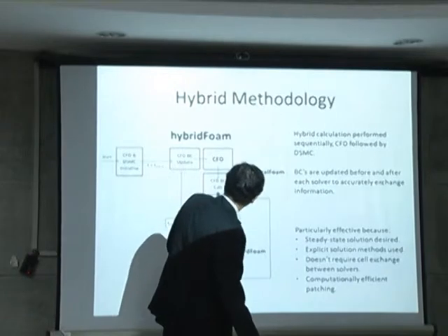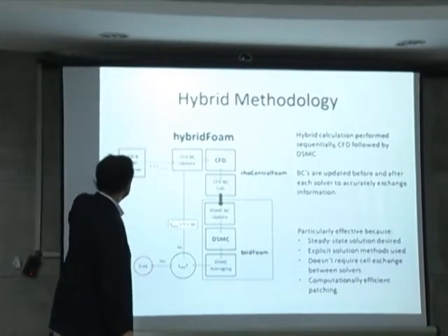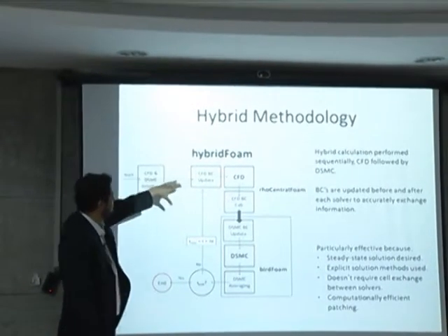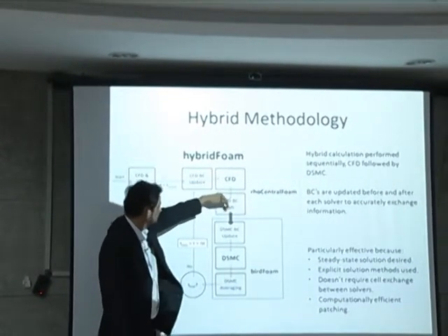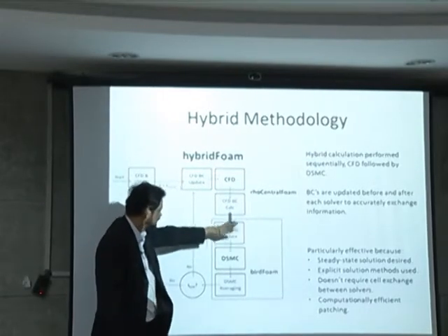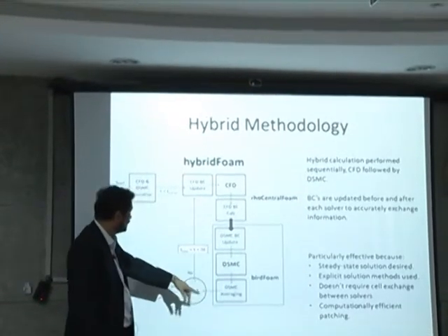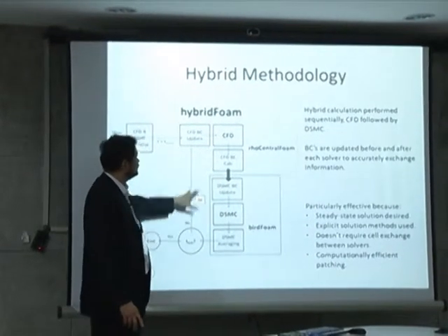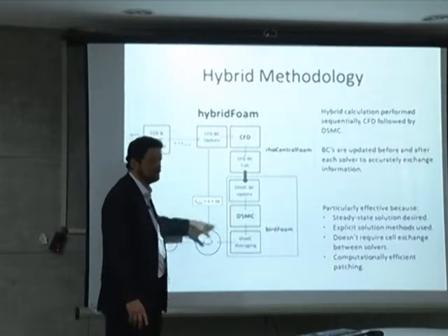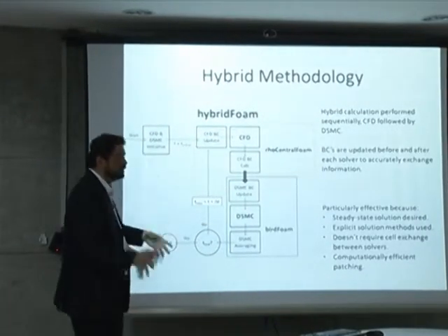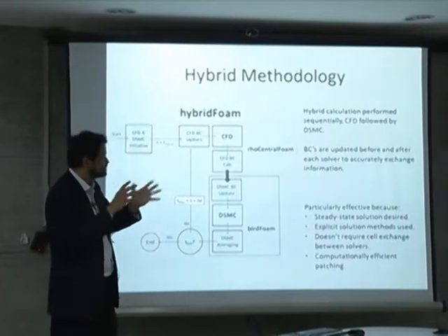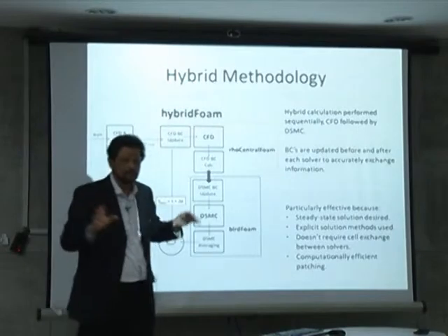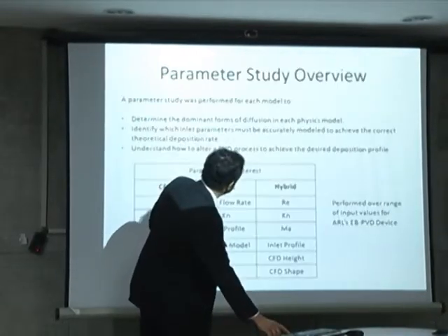It becomes highly numerically intensive, and this is the overall flow chart. You initialize, then you do the CFD calculation, then you go into the DSMC region and do the calculation, and you check whether it is still a continuum region or not. If it is a continuum region, you do CFD and you keep on doing that. If it is not a continuum region, you call it direct simulation, then you stop there and define a boundary there, and you go on defining the problem from there. And then finally we have some comparisons.